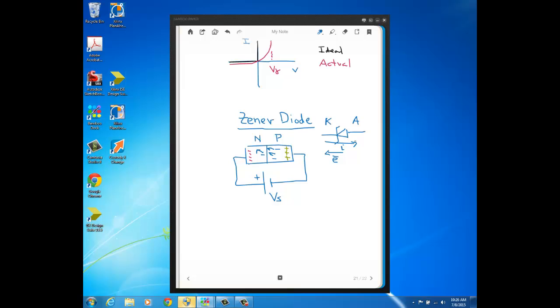It's very important to make the distinction that before today's lecture, we only talked about forward bias current, which flows anode to cathode, okay, over in this region of the IV curve. But here we have a current under this special condition, and it only works for a Zener diode, because if we don't have a Zener diode, the junction's not going to be strong enough and the diode will become defective. So you see, Zener diodes are specially fabricated to be able to withstand this avalanche current and remain robust enough where they still will function.